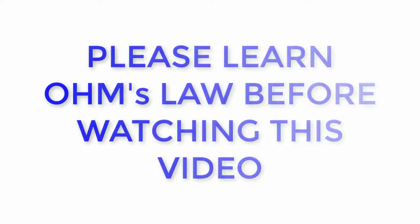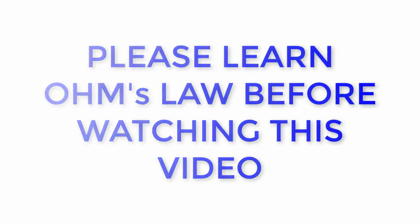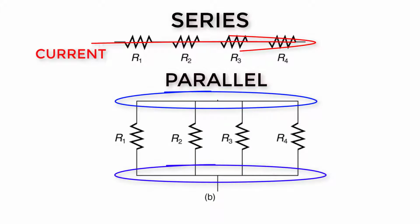If you haven't seen my previous video about Ohm's Law and you're not sure how it works, please visit that video first before you watch this video. Just to recap from the last video, components such as resistors are said to be in series when they are in a row with only one path for current to flow. They can be combined into one resistor by adding them together. On the other hand, components are said to be in parallel when each side of each component is directly connected to a node with each side of the other component. Parallel resistors can be combined into one resistor using the following equation.